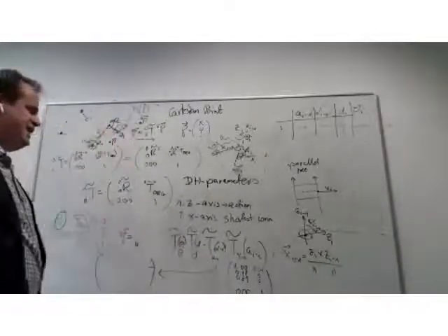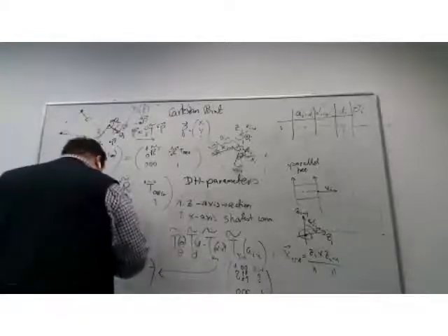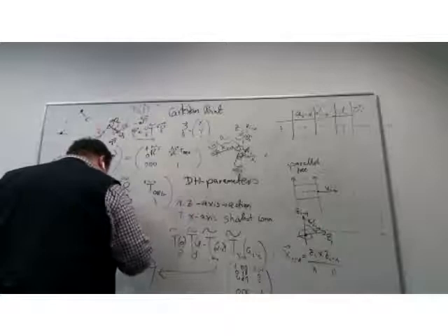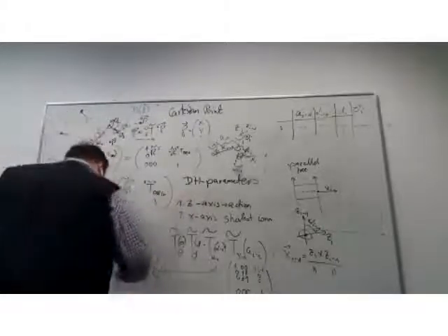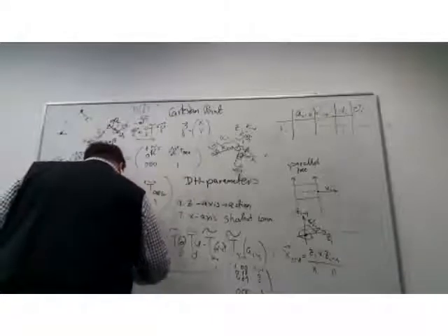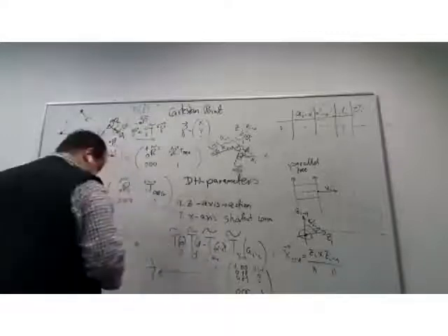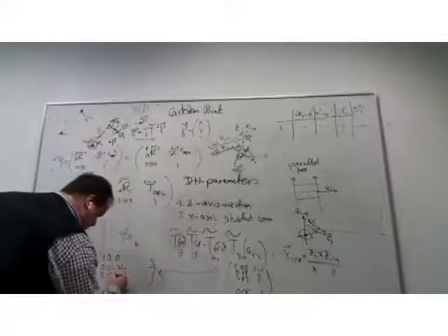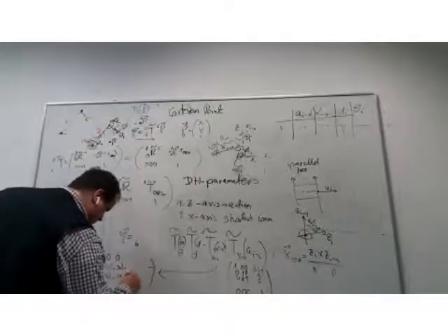Take the matrix for rotation around x by an angle alpha. Because it's rotation around x, the rotation matrix is one of the elementary rotation matrices we just discussed. So cosine alpha_{i-1}, minus sine alpha_{i-1}, sine alpha_{i-1}, cosine alpha_{i-1}.